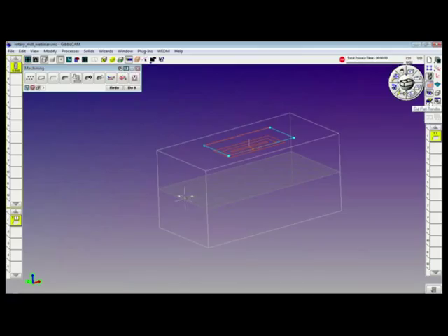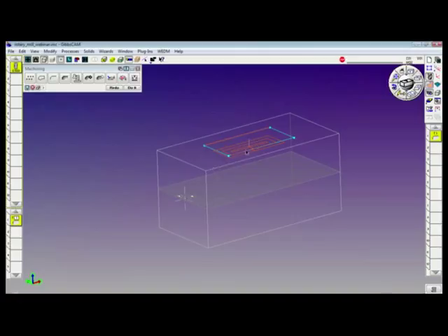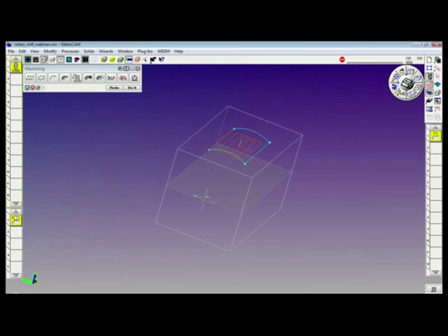If I render it, we're going to see the tool path start in the center and give us a nice flat cut. Now, if I was doing wrench flats, this would be ideal. I'd put one up here, duplicate it and rotate it 180 degrees at the bottom, and I'd have wrench flats. But that's not the intent. The intent is to create this pocket in rotary mode. If I wrap the geometry, we'll see the effect that I'm looking for.